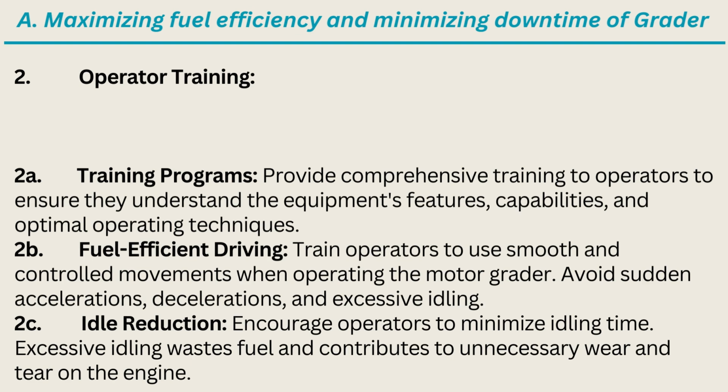2. Operator training. 2A. Training programs. Provide comprehensive training to operators to ensure they understand the equipment's features, capabilities, and optimal operating techniques. 2B. Fuel-efficient driving. Train operators to use smooth and controlled movements when operating the motor grader. Avoid sudden accelerations, decelerations, and excessive idling. 2C. Idle reduction. Encourage operators to minimize idling time. Excessive idling wastes fuel and contributes to unnecessary wear and tear on the engine.